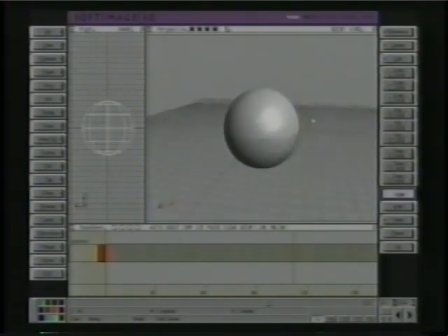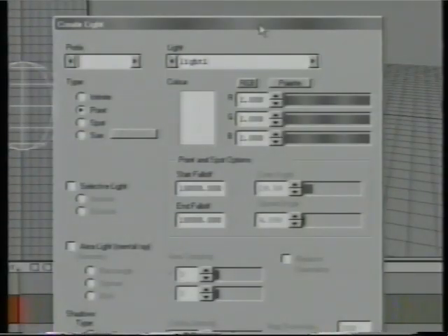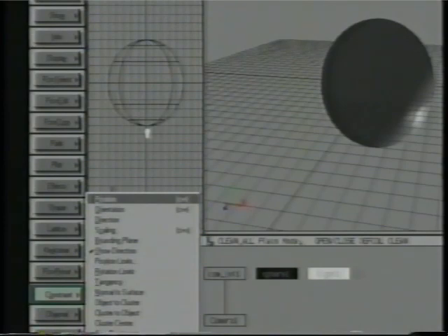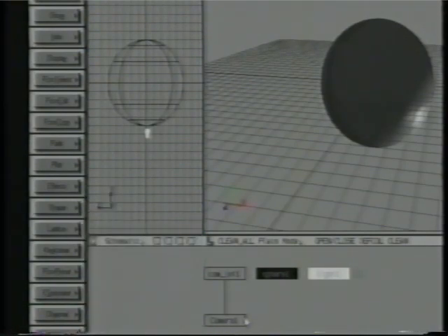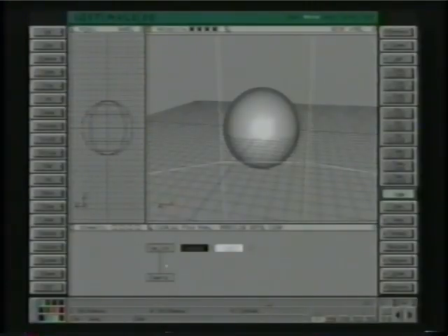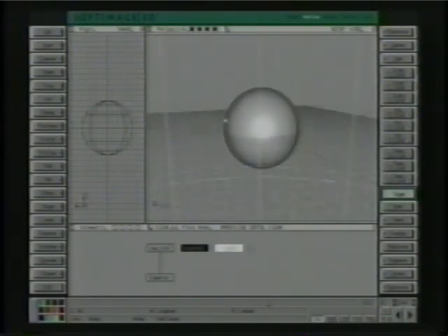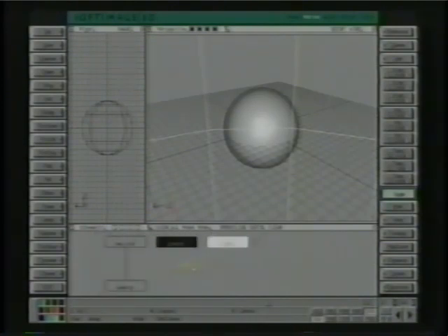one thing you can do is add one light to your scene. We can just accept the default parameters. Now, with the light selected, go to Constraint, Position, click on the camera. Now the light is constrained to the camera. Wherever we orbit around the scene, the light will stick on the camera, so there will be no dark side. So if I turn on here model mode, you can see the relationship. The light is constrained to the camera. This winds up being really handy.